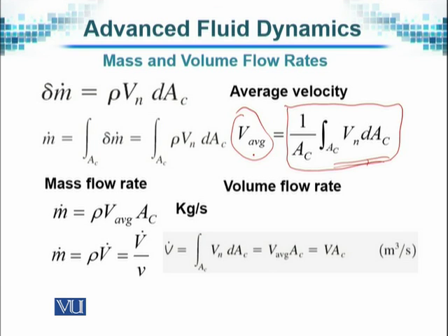Since the surface is changing, the area may be changing, so we need to integrate within the limits, and therefore it is shown in integral form. The mass flow rate, of course, is given to you already in whatever units are under consideration. Mass flow rate is equal to rho times the velocity, which can also be written as V dot over nu, and similarly these equivalent values will be used from time to time.